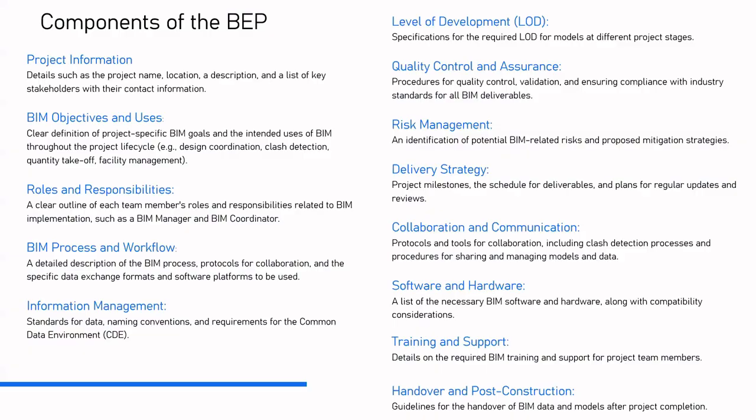So it looks at the design coordination, the clash detection, the quantity takeoff, but more importantly is what is this data actually going to be used for at the end of the day? Once that as-built information is handed over to the procuring authority or the client, what is going to happen to it? Is it going to be used in future? Is it going to sit in somebody's drawer on a flash drive? Is it going to sit in a cloud server somewhere? The real benefit comes down to facilities management actually fully embracing this BIM handover information and using that as part of their ongoing management and expansion or maintenance of the facility.